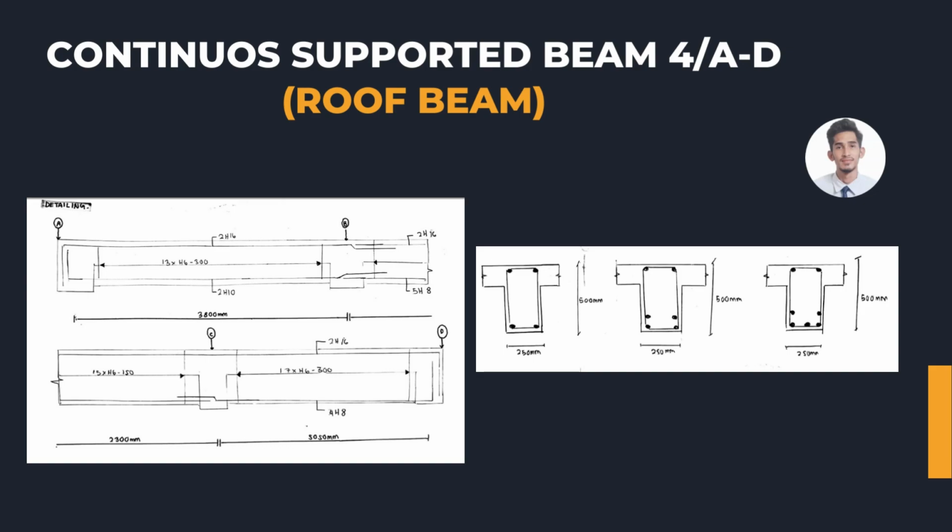So this is detailing for the beam 4A. For the beam A to B we use 2H16 on the top and 2H10 for the bottom, with H6 at 300 link spacing. For the beam B to C, we use 2H16 on the top, 5H8 for the bottom, and the link is H6 at 150.